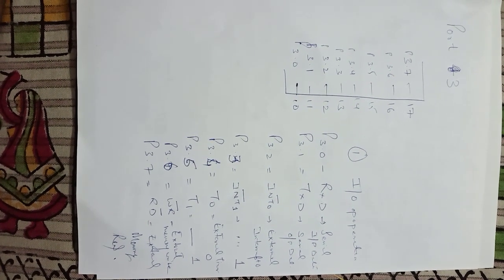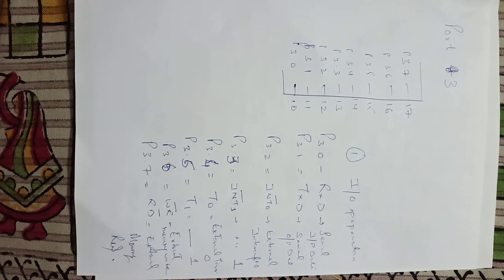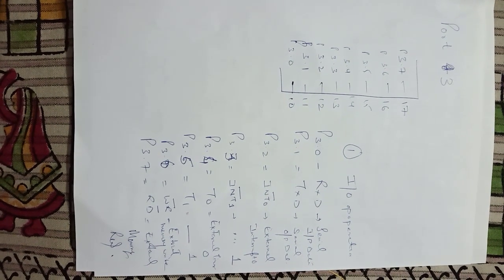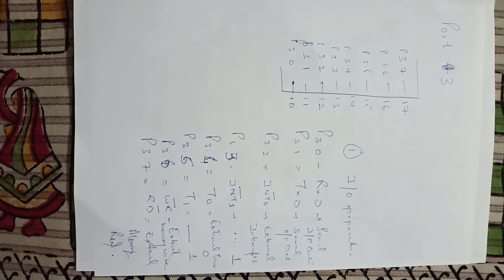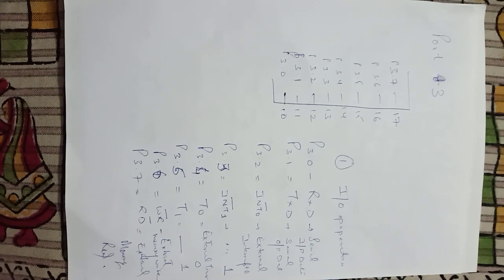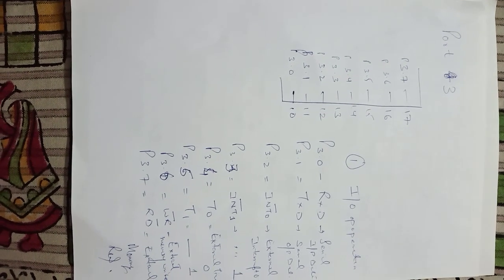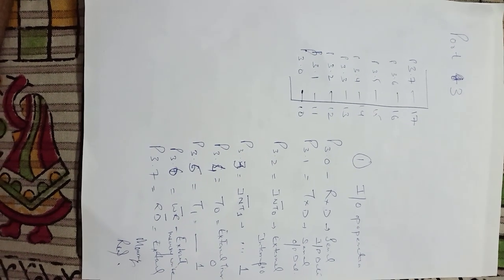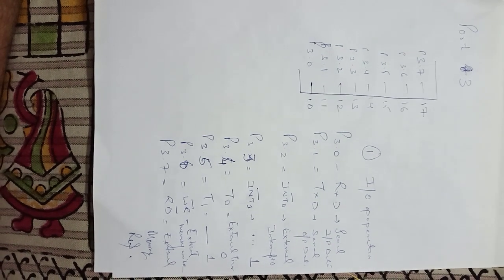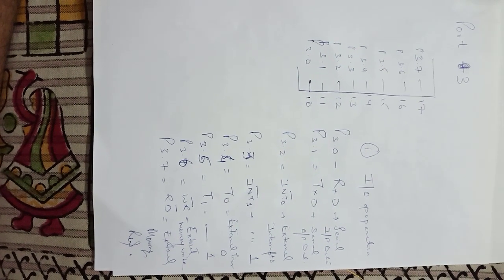For external writing and external reading of memory or any other peripheral, we have two specific port pins, that is P3.6 and P3.7. So in this way, all the ports are discussed and their structure is defined. They can be used for input output, or for generating the address bus or data bus, or as special pins for special function registers.